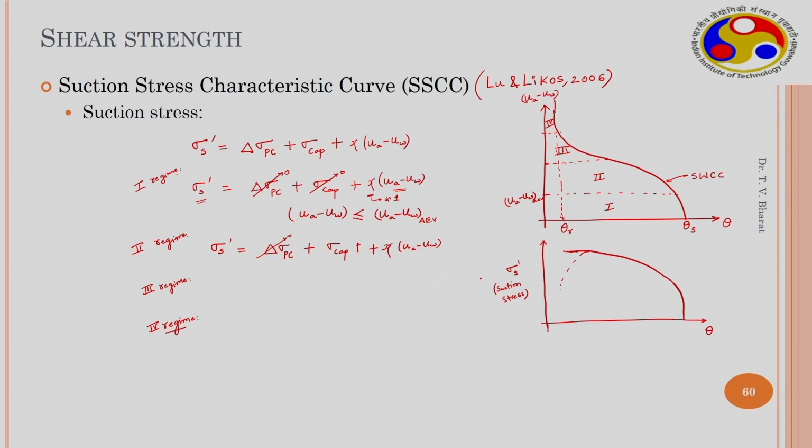water is held as thin films around clay platelets. The amount of water that is available in the soil is only available for hydration of exchangeable cations and hydration of the different inner layers of clay platelets. You will have multi-layer hydration, that is, water equivalent to multi-layer hydration is available in clays, and a single layer of hydration may be available around sand particles.